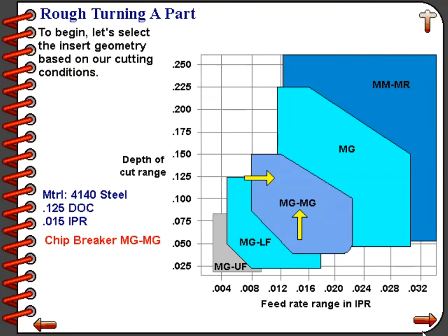You will really need to refer to different documents or different books that explain how to calculate the horsepower based on the cut. Most tooling vendors provide you with slide rules or other formulas or calculators that can help you to determine the horsepower of cut.